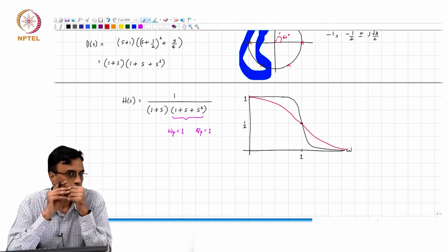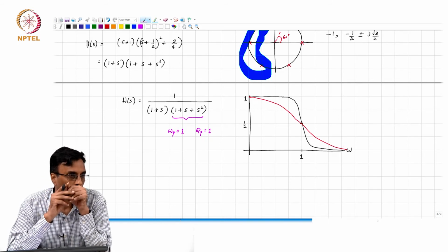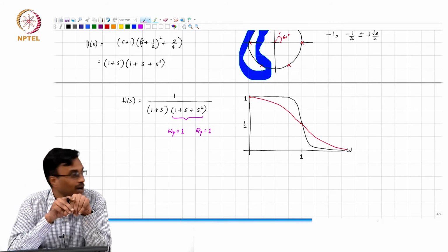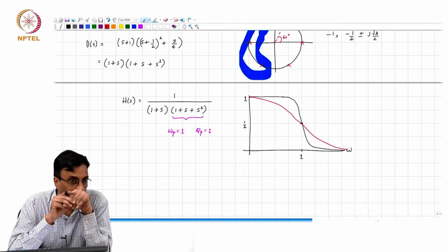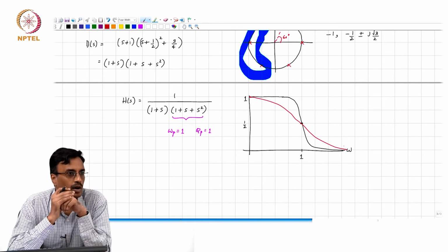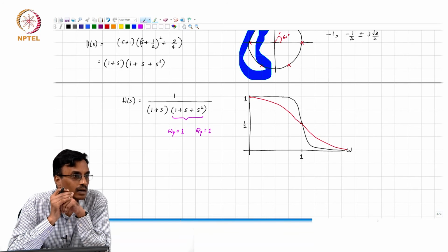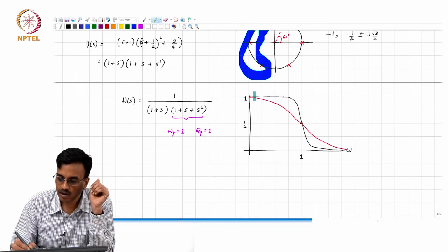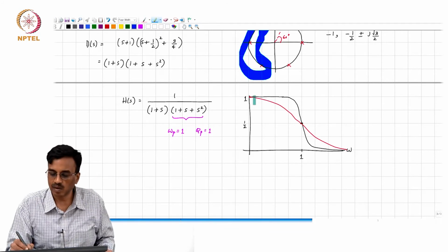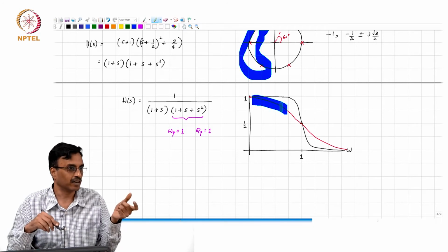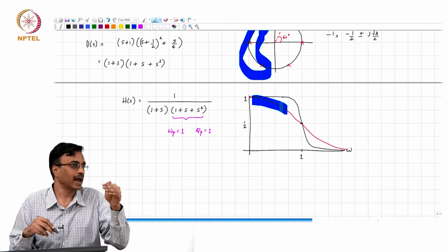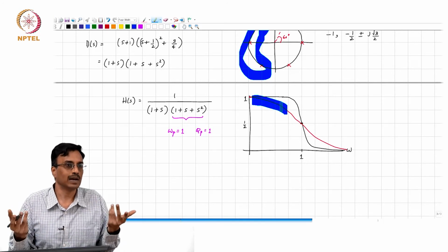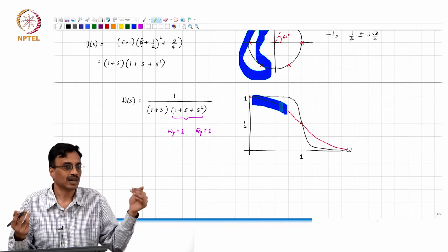Pardon? So, okay, let's start at the origin. What will it be at the origin? 1. Okay, slightly beyond omega equal to 0, how will it look? Huh? Okay, the one answer I got was, oh, it will be flat. Okay. So, remember, the total response is the product of the first order response and the second order response, right? If the second order response is flat and the first order is falling, what will you get if you multiply the two? Something which is falling, right?